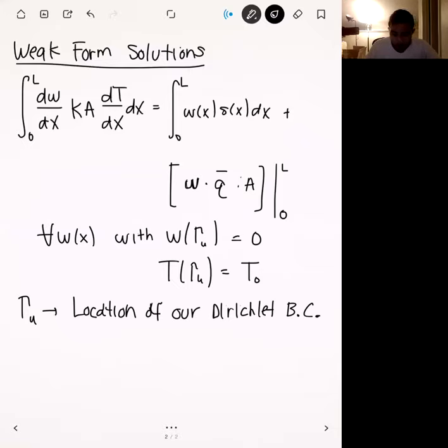All right. And so this is the form of the weak form for heat transfer. I know some people have gotten confused about applying this for heat transfer versus for elasticity. I want you guys to not worry about that because mathematically they're exactly the same thing. You're going to have the exact same equation here. It's just some of the symbols might be a little bit different. If we were doing this equation for elasticity, instead of the thermal conductivity here,